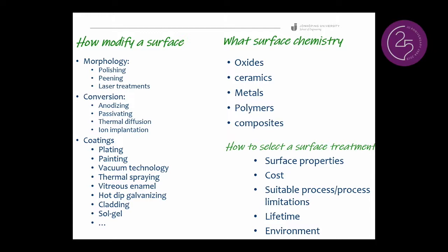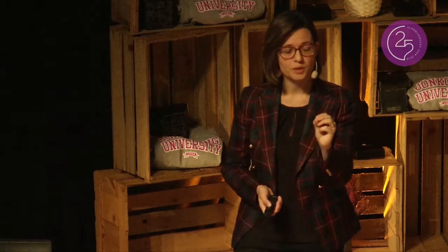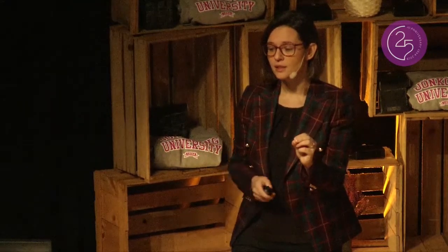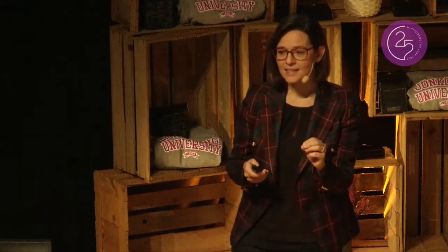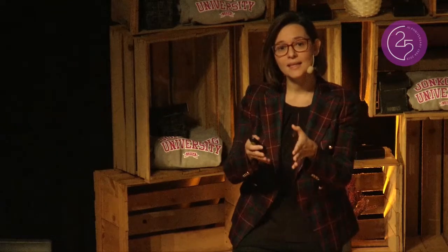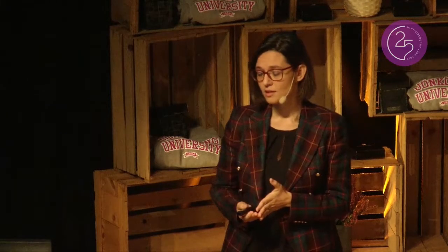Our way through it depends on identifying what you need first, identifying the surface properties that are needed, evaluating the cost involved in these treatments, understanding among the different materials and the different processes which is the possible and suitable combination, considering the material you are treating, considering its geometry, considering the limitations, and also considering the lifetime of an object, because nothing is infinite, but never forgetting that the surface is an interaction, interplay region.